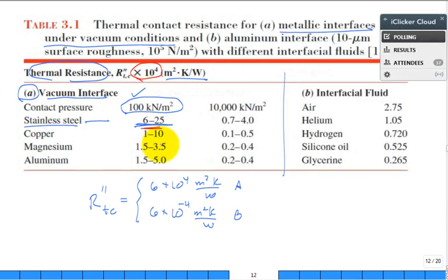So, all right. So now, this is also interesting. What is the difference between this column and this column? It's the pressure. It's that normal force per unit area pushing the two materials together. As I have a larger pressure, normal force pushing them together, does it help? What does it do? It reduces that contact resistance. Good, that makes sense. So a lot of times you clamp things together if you need it. Now this is all for a vacuum. And we just talked about, there's a lot of thermal paste to put in the interface. You keep it very thin, just enough to help a little bit.